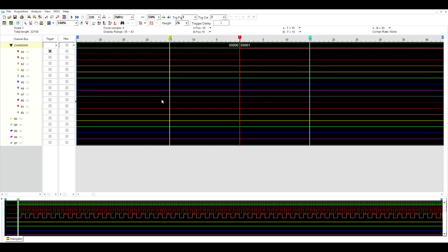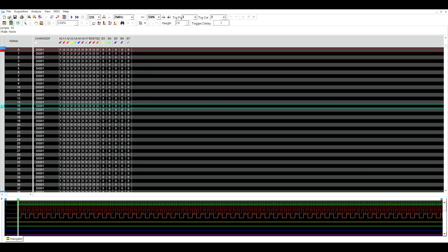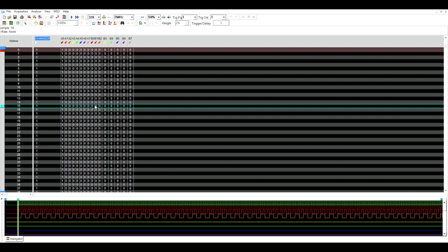But the video memory is not hooked up, so those inputs will default to 0. So all we will see here is the indexing, that addition of 0, 1, 2, 3, 4, 5, 6, and 7 to that base address that in this case will always be 0. So what we should see in this case is that index going from 0 to 7 and then back to 0 and up to 7 and back to 0. And each pass should stay there for 80 clock ticks.